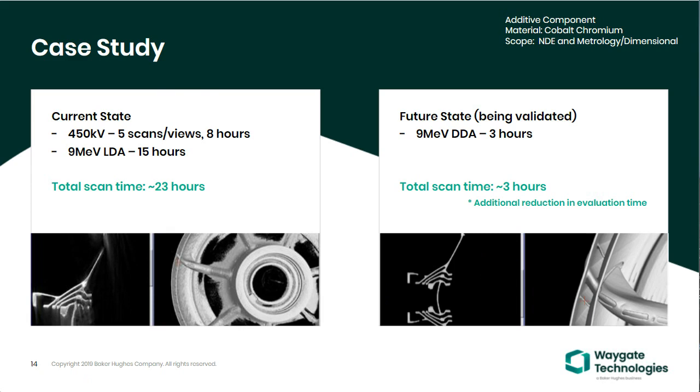Here's another one. This is the part that I showed you at the beginning. The current state of this component is something like five scans, or five different views, which are about 8 hours of scanning on a 450 system, and then moving it over to an LDA system that's 9 MeV, that's about 15 hours. So this one component has about 23 hours of total scan time to get it validated properly.